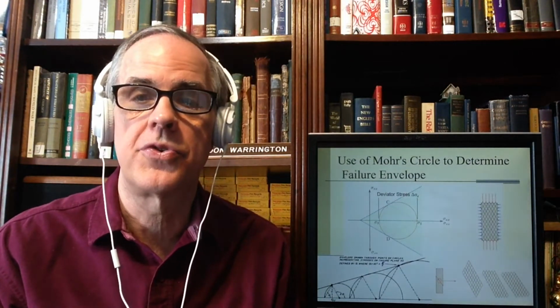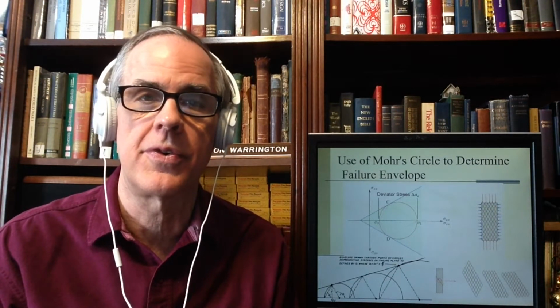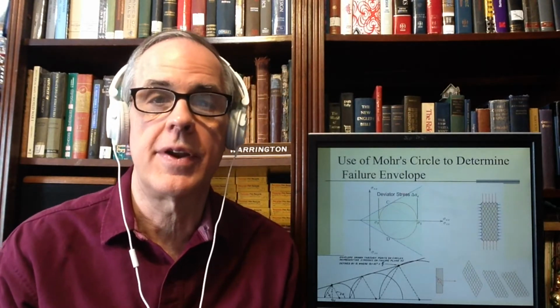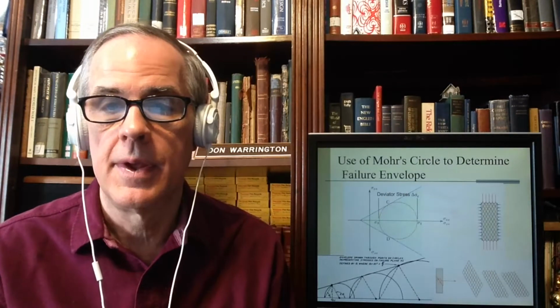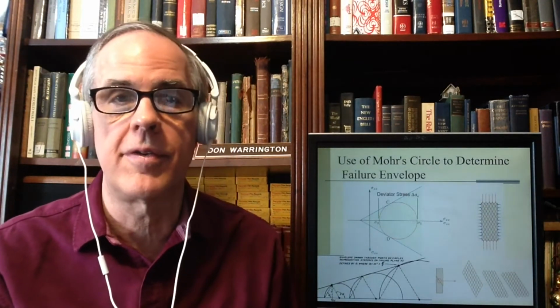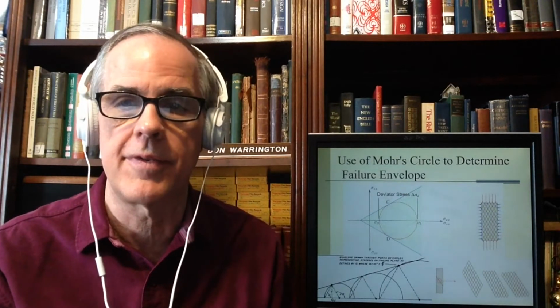And therefore, you can determine its Mohr Coulomb properties. You can do this for any number of conditions. You can do it for either drained or undrained conditions. Note, again, this is the definition of deviator stress, and I've gone over this several times, but there it is graphically.